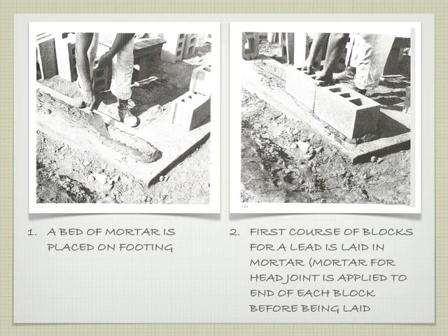The purpose of the footing, you guys remember, is to transfer all the load down into the soil. So we're spreading out the weight that's coming down into an allowable stress that the soil can support. Okay, so we have that footing. We spread our bed of mortar on top of the footing to tie these blocks to that.